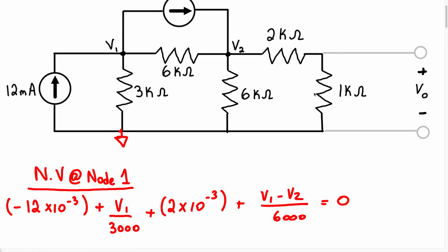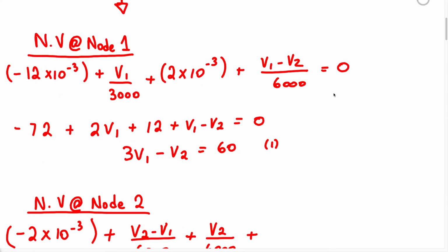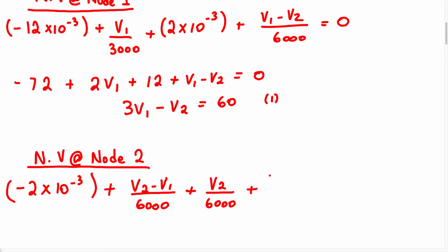So once we add these two resistors, we know this resistor and the equivalent resistance is going to be parallel, which means the same voltage that is in this 6K resistor is going to be in the equivalent resistance here of 3K. So when we find the current in this particular branch, we're going to have V2 divided by 3,000, and all of that equals 0.